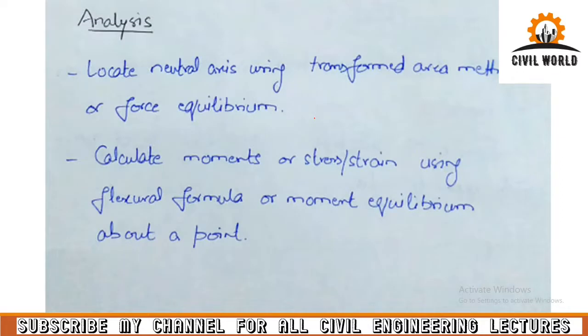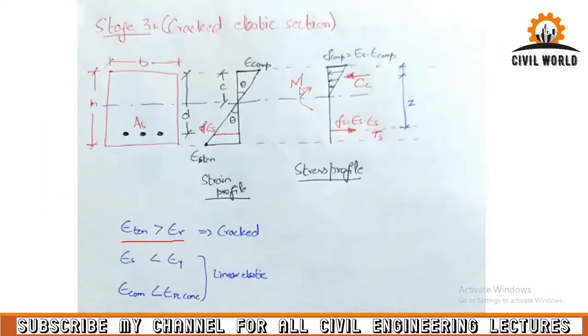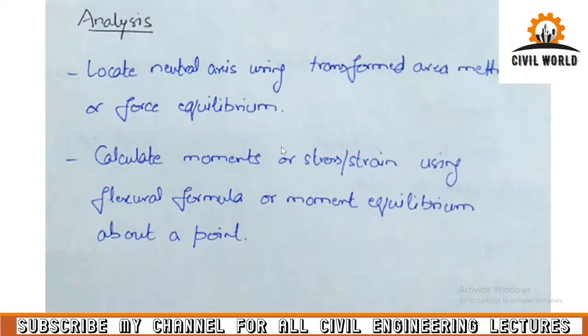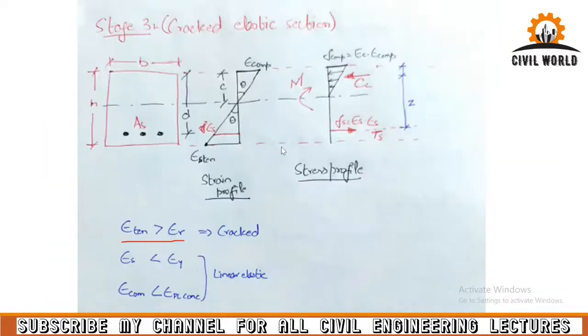So you can again use a similar procedure. You have to locate your neutral axis, calculate the value of c using the transformed area method or the force equilibrium method, and then you can calculate your moment, stresses and strains by using the flexural formula and moment equilibrium.